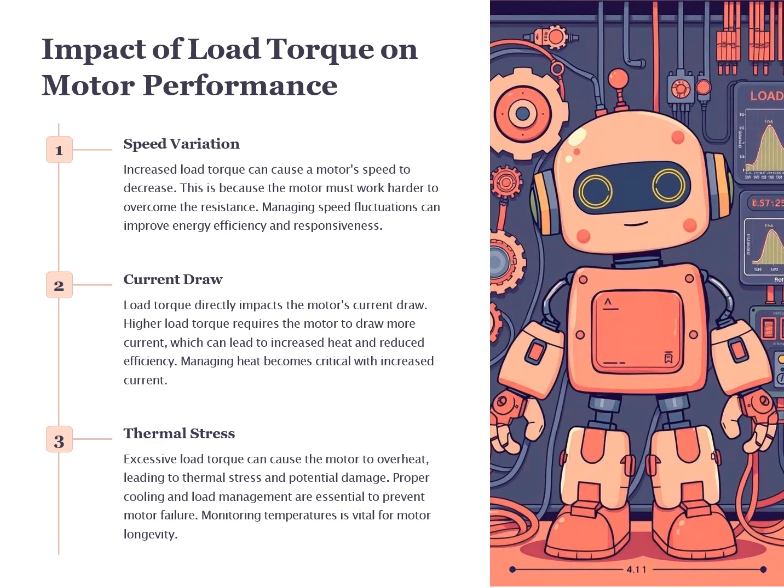Finally, the thermal stress is a major concern. Excessive load torque can cause the motor to overheat, leading to thermal stress and potential damage. Proper cooling and load management are essential to prevent motor failure and ensure longevity.